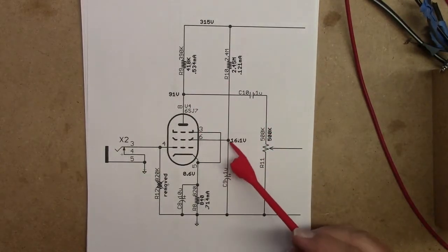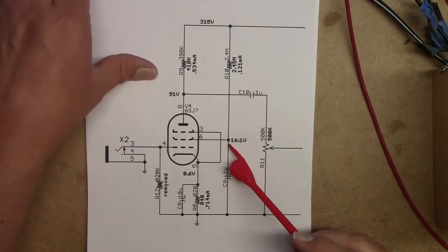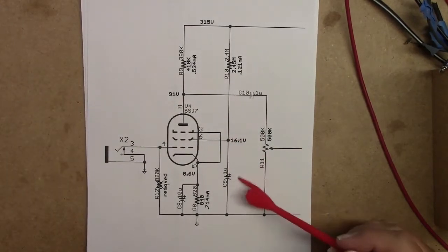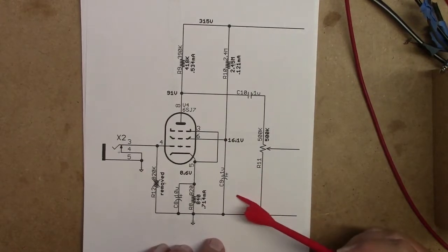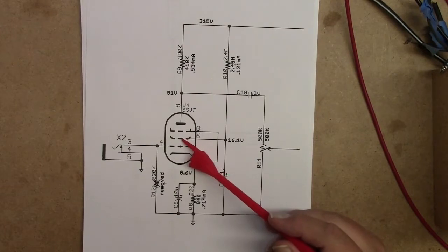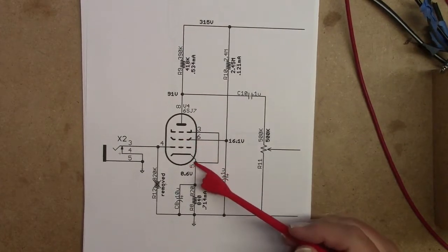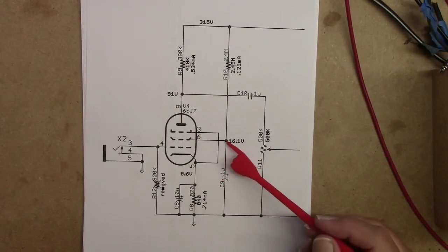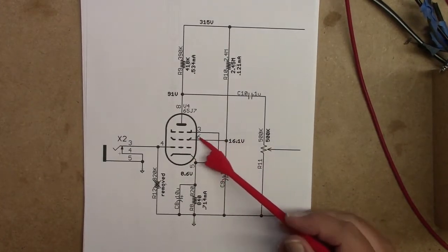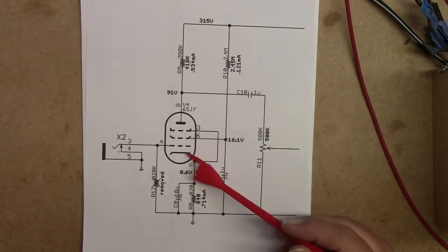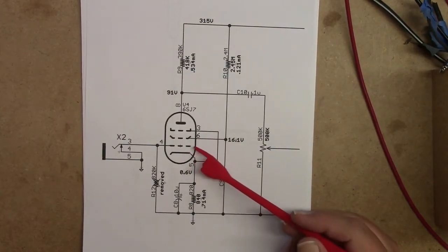So measuring this voltage here is actually pretty interesting, because if you think about it, if you put your meter in right here, there's a 10 megohm resistor right here, and there's effectively a resistance from the screen down to the cathode. And so you have a voltage, and then there's a current that runs through here. So this is effectively a resistance from a DC bias perspective.